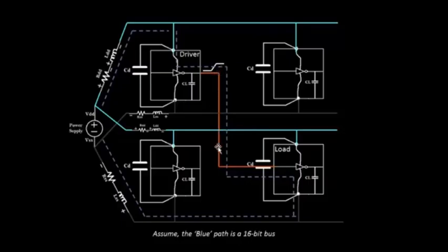Now for this line to retain the same scenario, it should get the necessary supply from the power, because in this region we don't have any decoupling capacitor that will take care of this scenario. So since we don't have any decoupling capacitor in this area, the power supply is the one who has to supply power to this complete line.